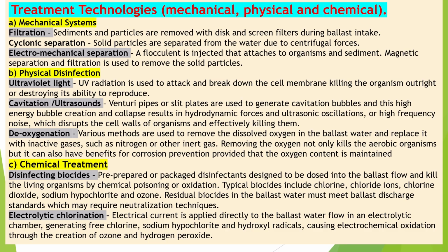A. Mechanical systems. Filtration. Sediments and particles are removed with disc and screen filters during ballast intake. Cyclonic separation. Solid particles are separated from the water due to centrifugal forces. Electromechanical separation. A flocculant is injected that attaches to organisms and sediment. Magnetic separation and filtration is used to remove the solid particles.